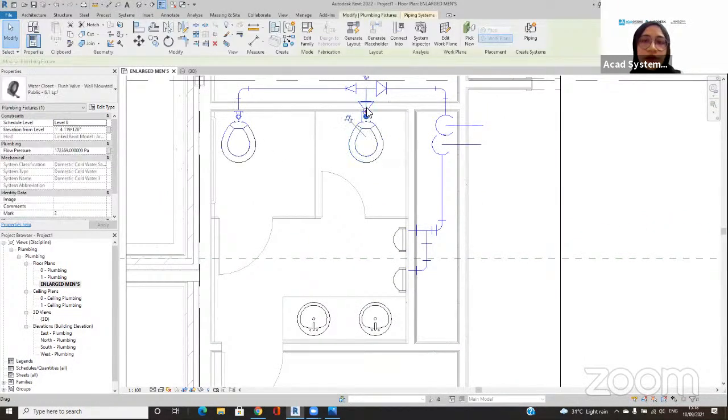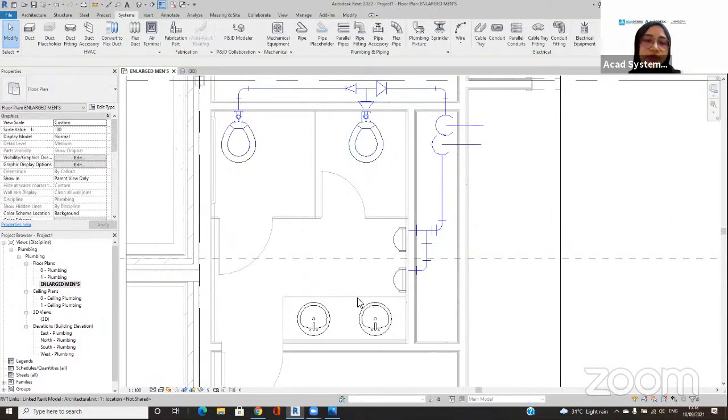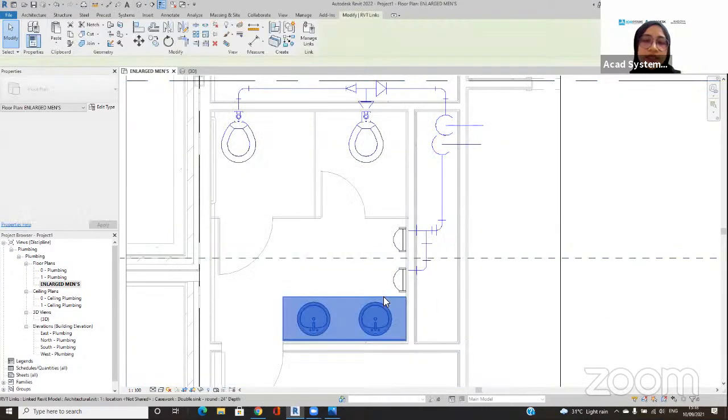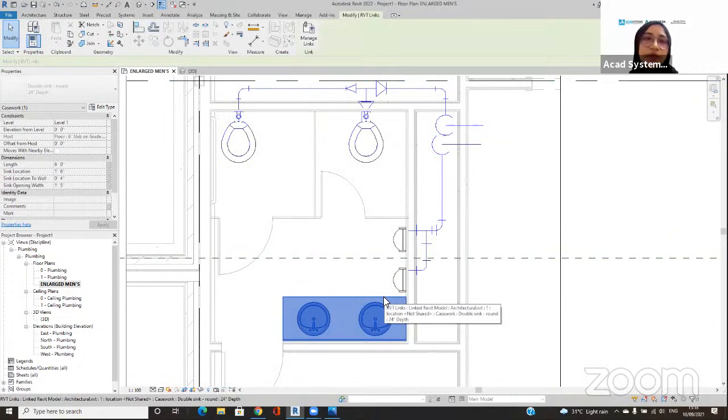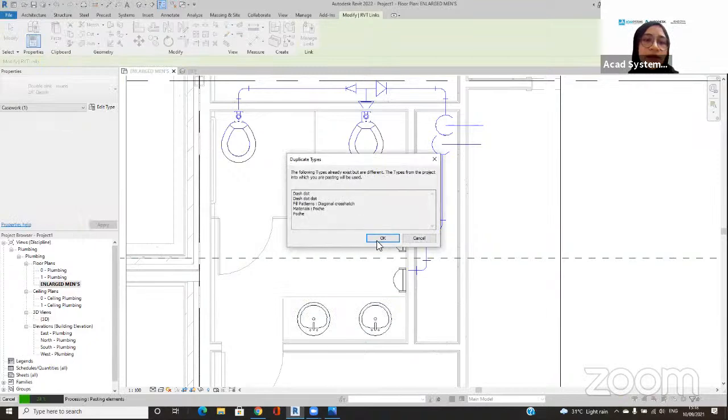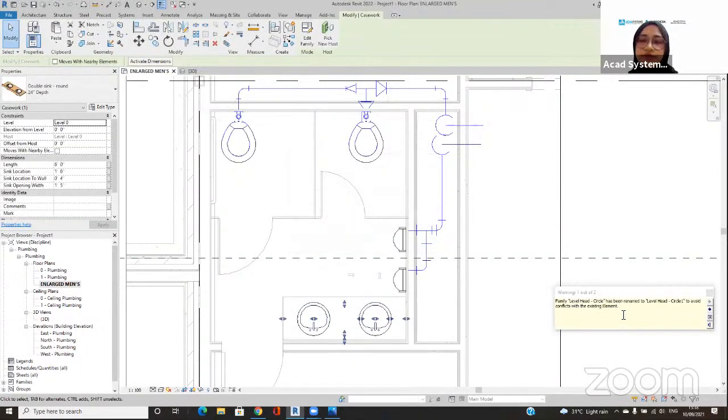So for here, they already have their own connector. For this architecture model that doesn't have one, we can edit them inside the family. I can click on this architecture model again, and copy first from this link. So I copy and then paste on the top here to the same place. All right. Yep. And that's fine.